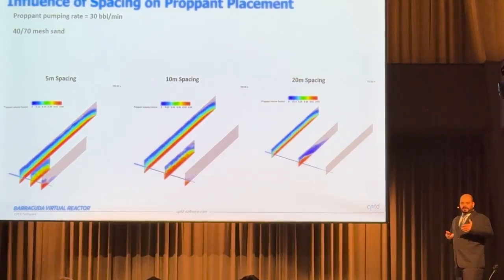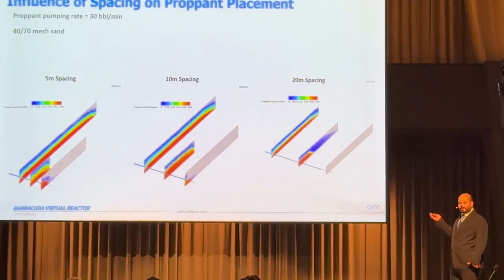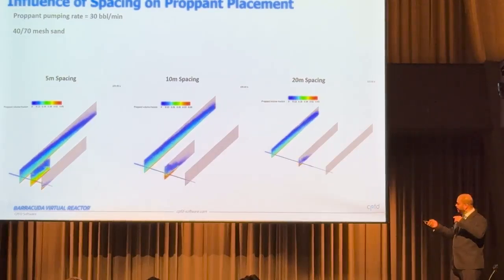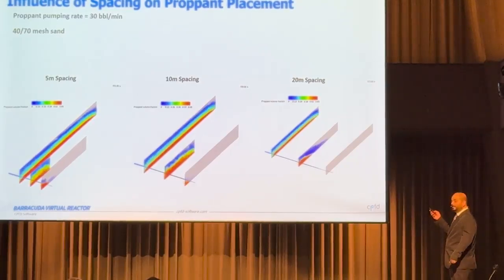The physics, there are no reactions in there. It's probably not as complex as some of the fluidized reactors you're working with. But nevertheless, this is quite important physics to look at, because we are not looking at single phase flow distributing among, like, a T-junction. This is slurry flow with solids in there. So you have to account for both the frictional losses of the fluid as well as the effect of the solids on the wall, along with the interaction between the solid and the liquid with non-Newtonian drag. Okay, fair enough.